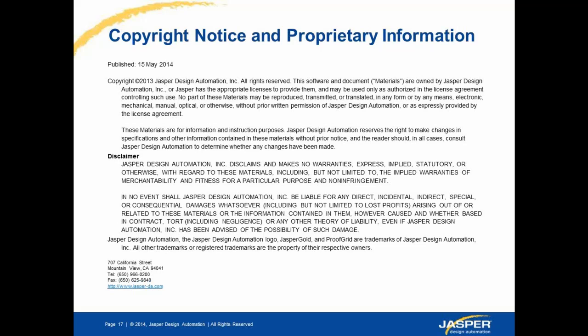I always wonder how these formal metrics tell us which simulations we don't need to do anymore. Is there any way of using these coverage metrics to say, you can now stop doing this type of simulation because now I know I've done this formal proof? I can cut out a certain amount of simulation. Because at the moment, formal is quite often an add-on. And if you go to your manager, what you really want to be able to say is, I can save simulation by doing this formal, and here's the proof of these coverage metrics. So do these coverage metrics help me go to a manager and say, you can stop doing this type of simulation?